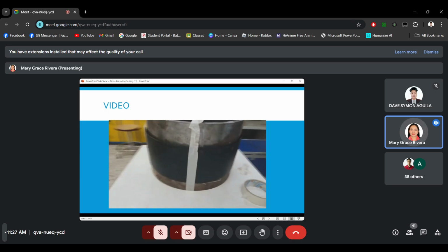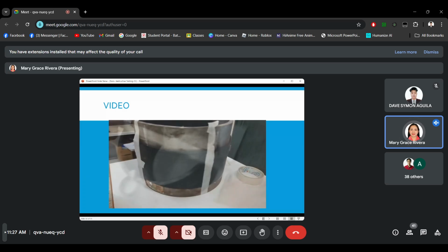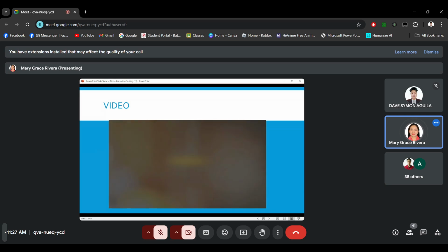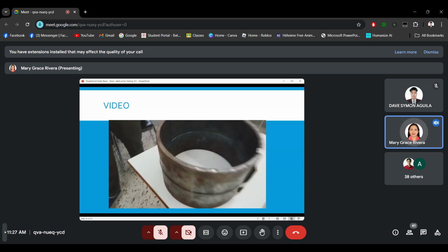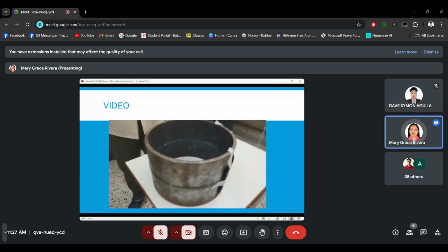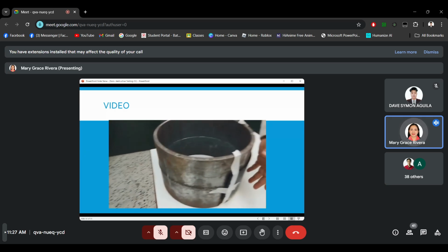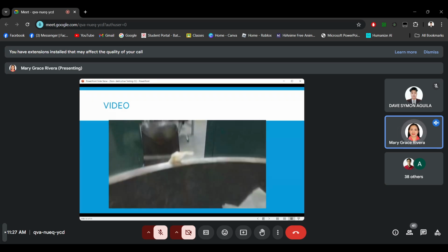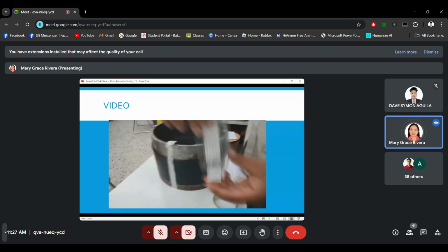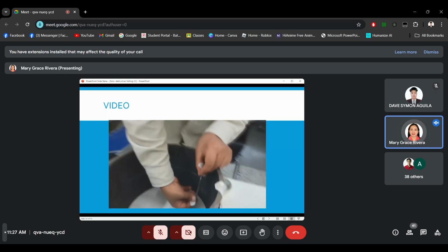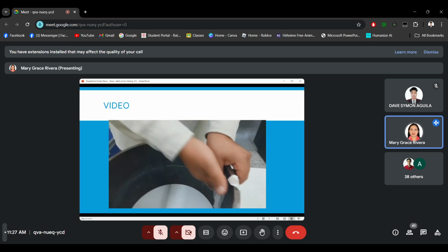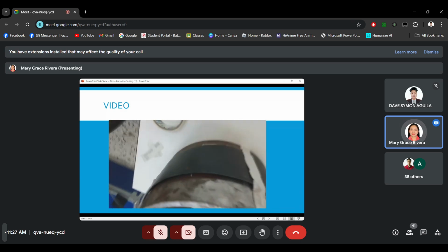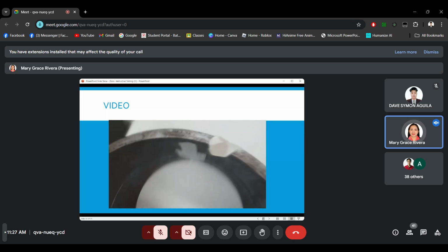Second technique is panoramic. It should be performed for pipe of outside diameter from 12 inch. The procedure is, after finishing film loading, start to perform this technique with visual inspection of the specimen. Examine the welded specimen visually and note down any surface defects. Use the appropriate IQI type according to the sample thickness, of the same material as that of the specimen. IQI should be placed in a proper manner on the specimen, i.e. source side and wires across the weld.